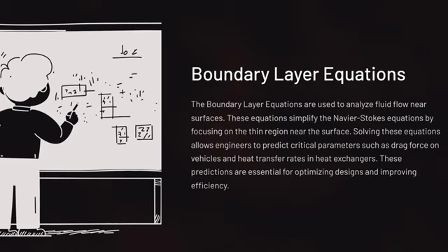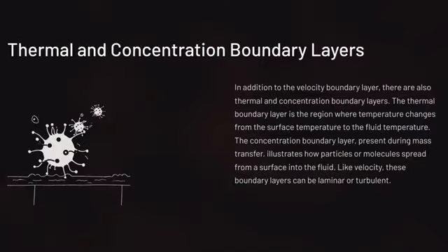And we use the boundary layer equations to analyze fluid flow near surfaces. These equations simplify the Navier-Stokes equations by focusing on the thin region near the surface. Exactly, and solving these equations helps us predict things like drag force on a vehicle or heat transfer rates in heat exchangers. And speaking of heat transfer, there's also a thermal boundary layer.